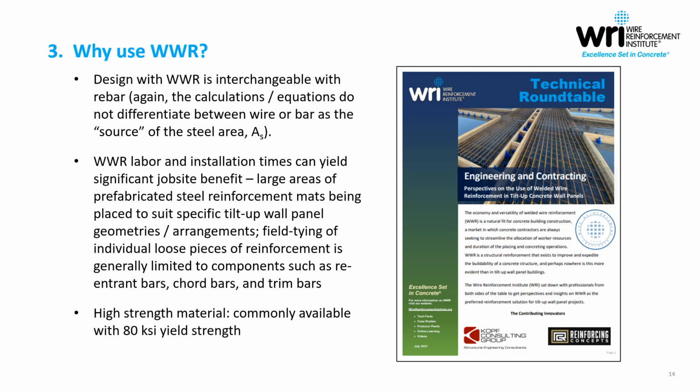And again, it's always worth reiterating that welded wire reinforcement is very commonly available in 80 ksi yield strength. That really doesn't require any level of premium from a manufacturing standpoint.